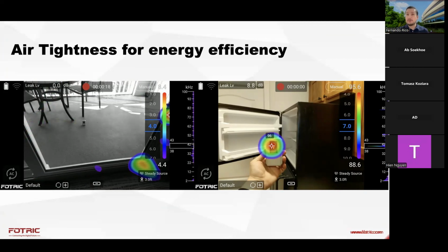And although thermography is a known technology to perform these tests, along with a blower door to create negative pressure in the entire building and see where air is filtering in, this is another technology that allows you to see missing insulation on the windows or gaps on the gaskets of the windows and doors, which will ensure that your building is properly sealed to prevent energy loss.